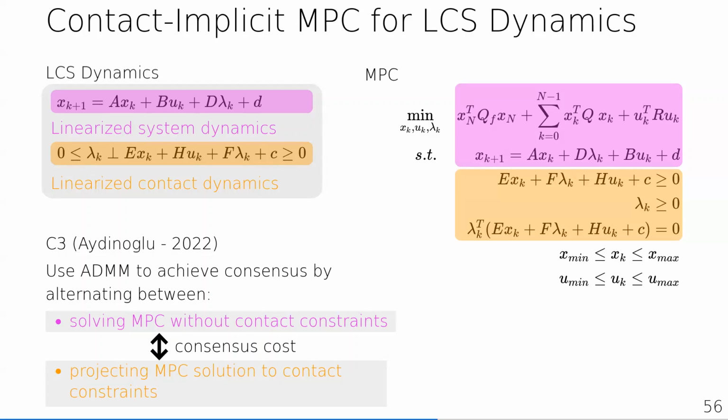Yeah, we don't converge. We solve a fixed number of iterations to get the speeds we want, and we're basically hoping, it's kind of the magic of Boston Dynamics, that for real-time control, by solving it fast enough, you get close enough to the solution that it doesn't matter.